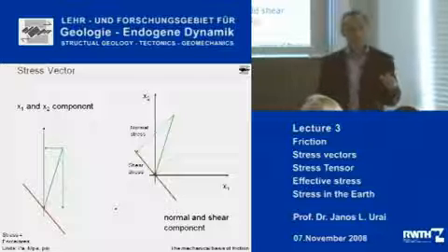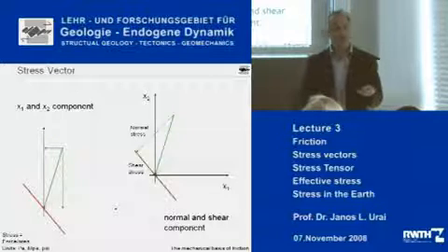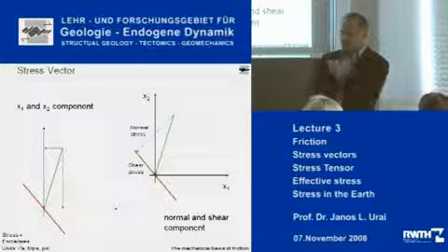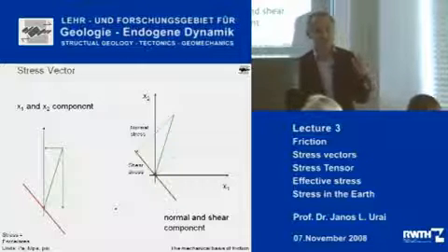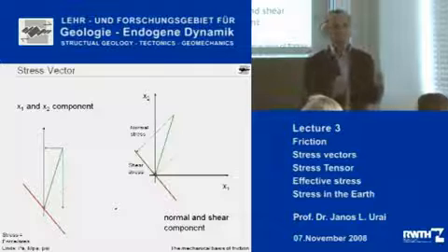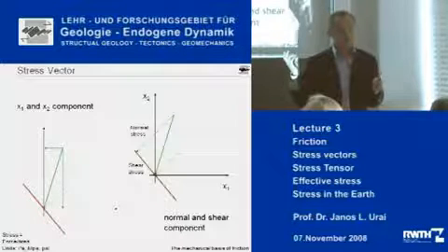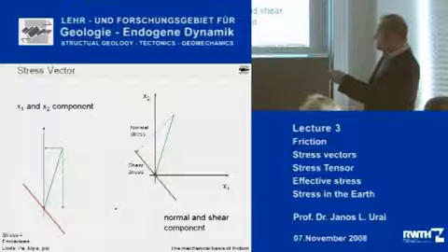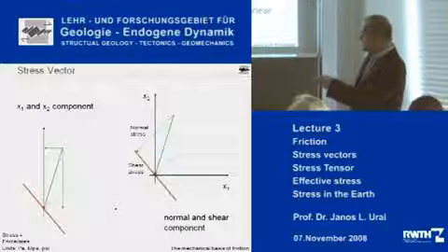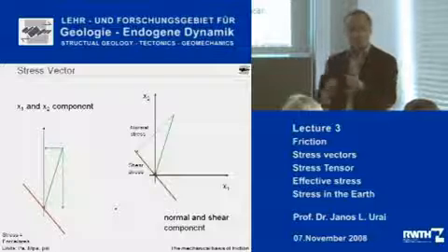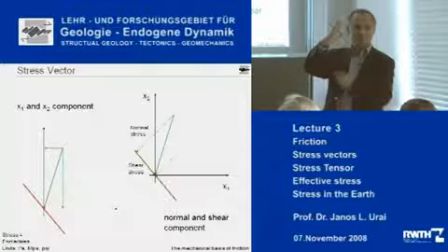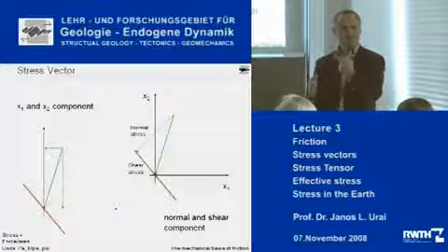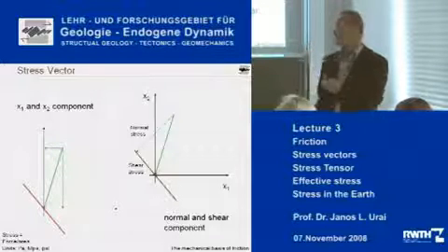This stress vector can be decomposed in a number of different ways. And one of the confusing things about this lecture, that is where you really will have to pay attention, is how you decompose the stress vector. I will decompose it in today's lecture in several different ways. So here's the plane, and the plane is defined by its normal. Okay, so this is the plane, and this is the plane normal. That is the thing that you use to plot in the stereogram the position on the plane as a point.